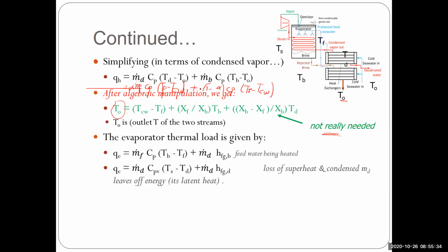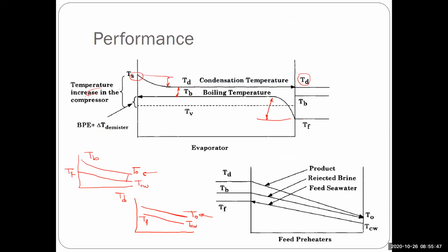But as a matter of fact, this equation and the previous equation that has been split into these two parts is what you need. What will happen inside the evaporator is that the Q evaporation will be looked at from two sides. You can look at the heat transfer in the evaporator from here. It is basically made up of two parts. So Q evaporator here can be m dot distillate or m dot vapor into Cp into (T steam minus T distillate).